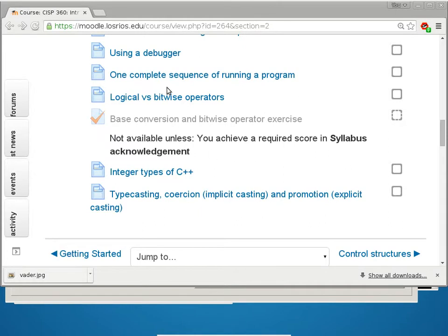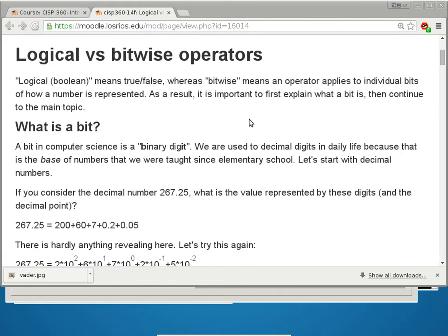All right. So last time, we talked about logical versus bitwise operators, and what Danny just demonstrated is a good example of why bitwise operators are useful. When you are dealing with a circuit board like that, the Arduino board, each pin on the outer part of the circuit board is controlled by 1 bit of one input-output register. So to turn on something, you just want to change 1 bit of one particular quote-unquote variable. So how do you turn on just 1 bit or turn off 1 bit of a particular variable?